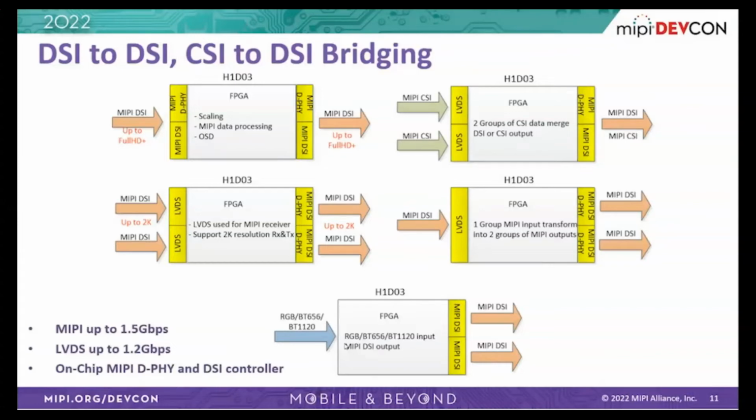As you all know, the camera data is a little different from display data. They have different commands, resolution, or frame structure. But if the camera's resolution ratio is similar to the display, for example 16:9, then it is possible to use FPGA logic to do this conversion. Even if the resolution is a little different, the FPGA can do the scaling. But if the camera resolution is quite different from the display, for example, you need to do some horizontal to vertical conversion, then the FPGA plus display memory can also do this conversion.